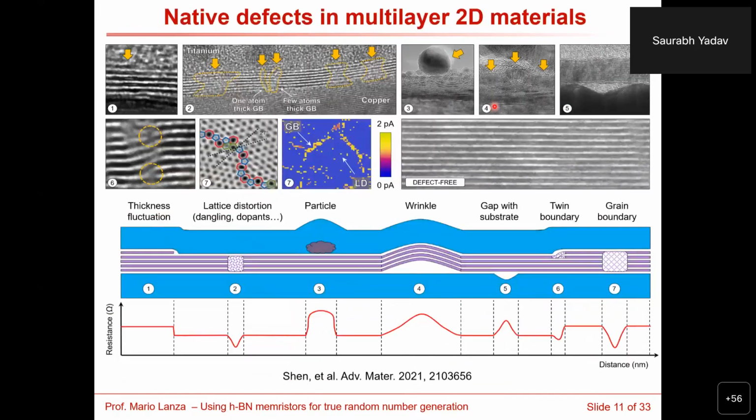So for the electrical contact between the 2D material and the electrode of the device, actually that is a whole science. That is one of the main problems hindering the fabrication of transistors, because that limits the mobility of the whole transistor. And this is an excellent question. There are many recent articles. There is a very famous one in Nature from MIT and TSMC that deals with this and achieves record mobility.